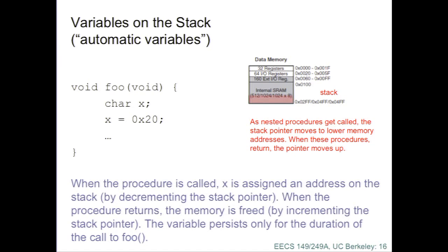There it is growing, right? And you have to be really careful to not overflow. Yeah. There's some processors that have a sort of a DMZ inside of the RAM that will detect when something is written to it and trigger an interrupt so you can handle it. Yeah, so higher-end processors have memory controllers that segment the memory and will actually trigger a hardware fault if your program accesses locations it shouldn't be accessing.